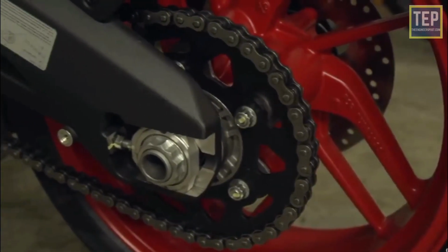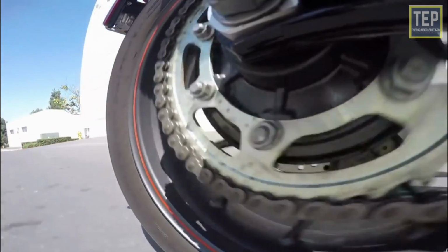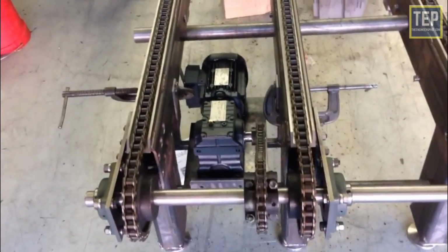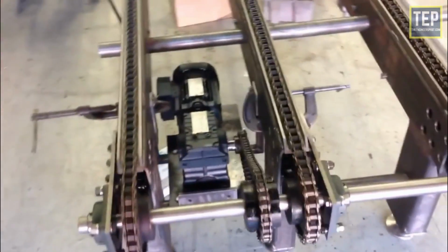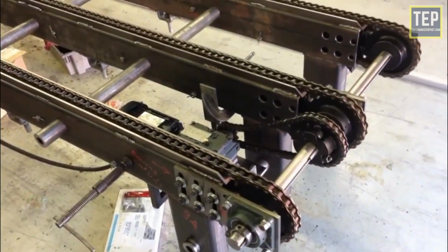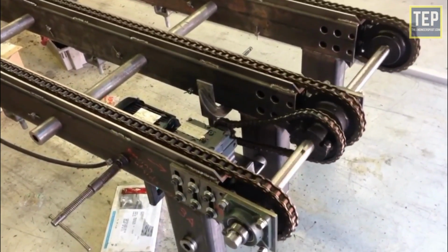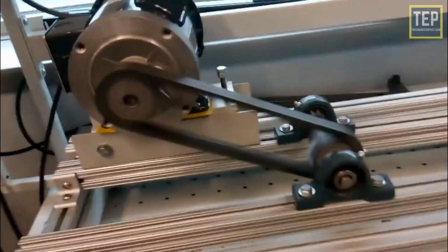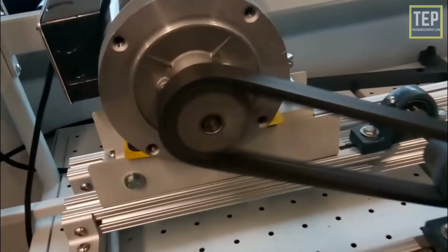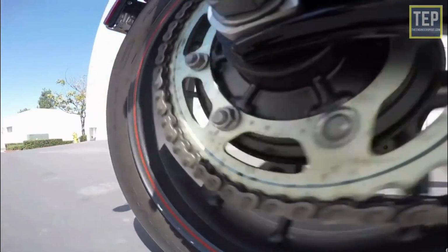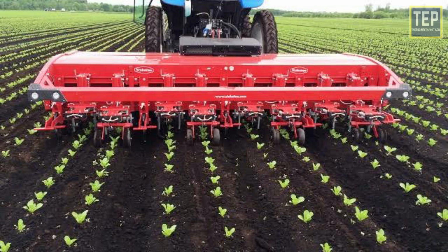Generally, a chain drive is used where the distance between the power produced is less. However, in some cases, we can use a chain drive for longer distances power transmission. In belt or rope drive, we see there is some percent of slip occurs, but in the chain, there will be no slip. But some amount of power loss we can generally see. Chain drives are employed for a wide range of power transmission, like in bicycles, motorcycles, rolling mills, agricultural machinery, etc.